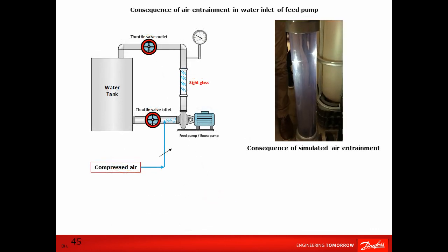The final test simulates what happens if gas comes into the pump inlet, for instance, caused by vortex in the water tank or leaky joints or seals. Air entrainment can occur if the pump inlet pressure is below atmospheric pressure, typically due to the shaft seals.